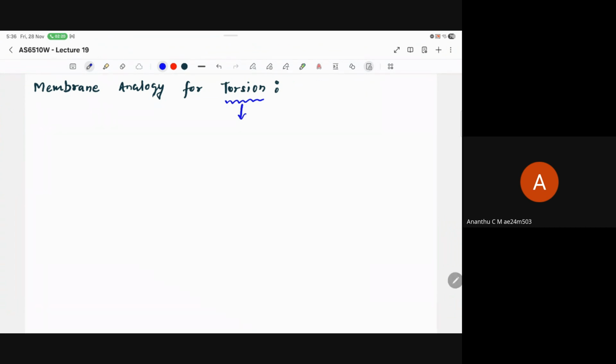So you can have a shaft. So basically, what we talk about is torsion of a shaft. And this is how we also define a particular structural element. When we talk about an axial bar, we mean a bar which is taking care of axial load, or which is having axial deformation. Similarly, we define a shaft on the basis of how it takes the load. A shaft generally takes the torsional load or torque. So that is why we discuss the torsion of shaft.